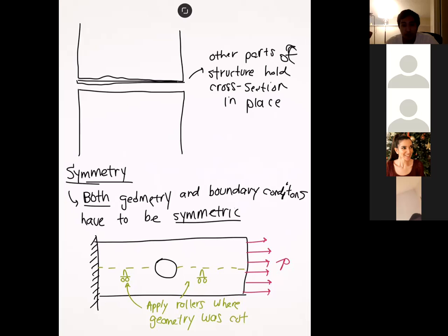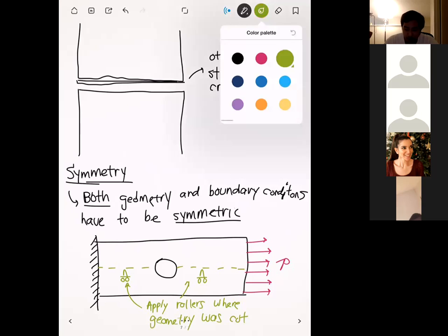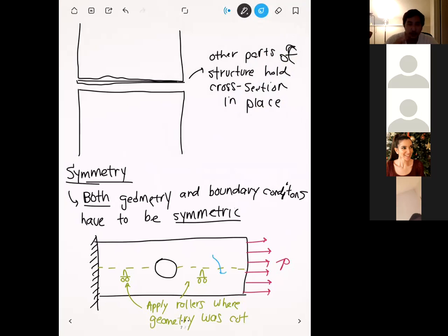Remember, the big tenet, or the big assumption, with symmetry is that you don't have any displacement or interaction going through this plane of symmetry, right? Because if the situation changed, say the loading was pointed down, and part of the structure displaced through that symmetry plane, then the symmetry no longer applies. Because if the deformation goes this way, then the bottom is no longer going to look like whatever's on the top. It really has to look like a mirror image on both sides.